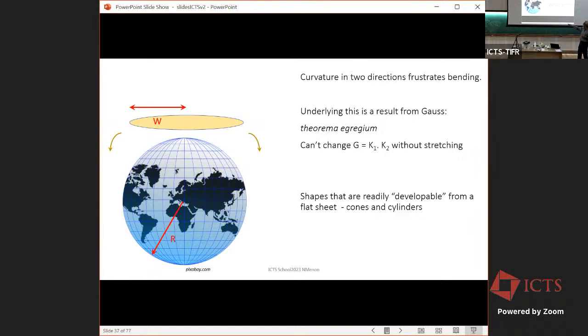So there is too much perimeter here. If this perimeter and the perimeter here don't match, there's less than 2 pi r here. At the top, maybe you sit flat. As you go further and further, there's a bigger and bigger mismatch between your length and 2 pi r. So you have to do something to get rid of that extra length. The first thing you do is you go in the other dimension and you make these ruffles. That's the first step of this process. Then you go further and that doesn't do enough for you, and then you go into these shapes that you're talking about.